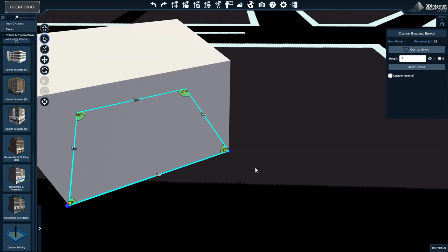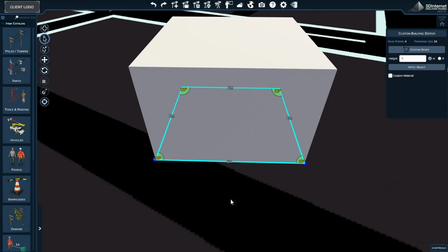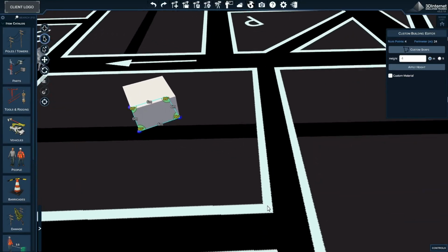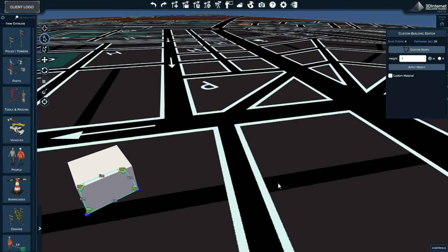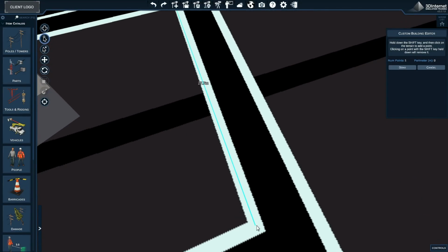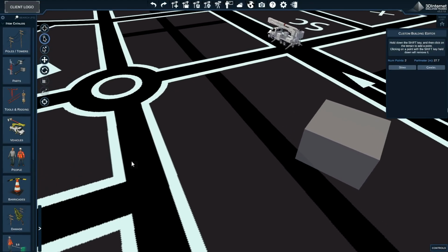We will now customize this building by specifying the shape of its footprint and then indicating how tall the building is. Start by clicking the Custom Shape button. Similar to drawing out the shape of a ground, we will hold down the Shift key and drop markers using the left mouse button. Notice how we are dropping markers around a building footprint within the drawing. While doing so, the length and angle of each segment is being shown.